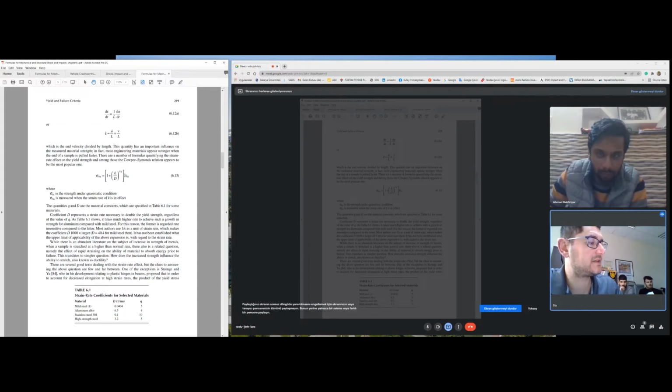The initial study of the explicit deformation used Cowper-Symonds. You can see the equation. For example, when you talk about the deformation, you can talk about the strain rate effects. Cowper-Symonds parameters. What is the Cowper parameter? What is the Symonds parameter? These are very important, Cowper-Symonds parameters. You can talk about this.